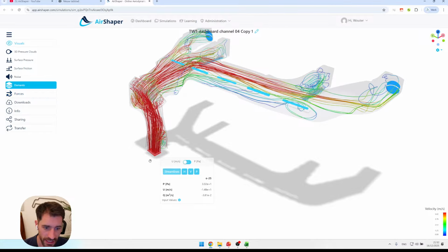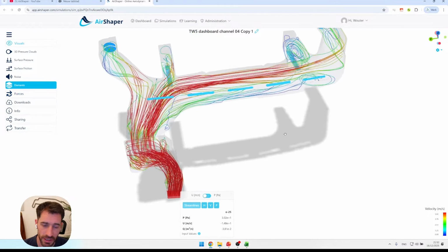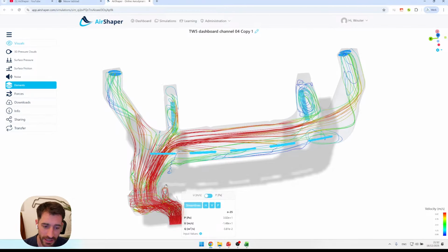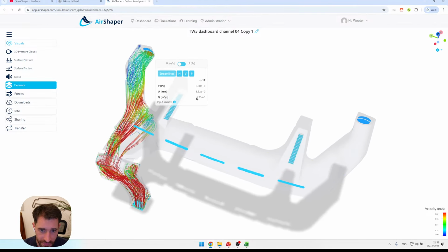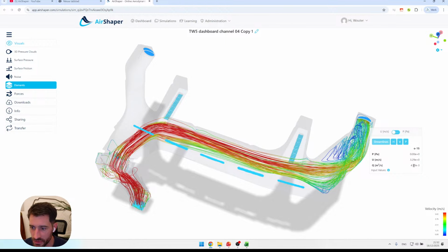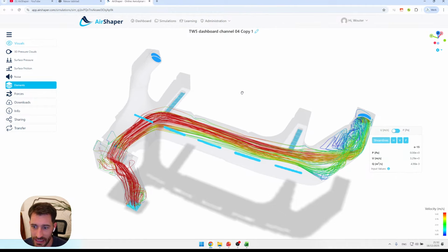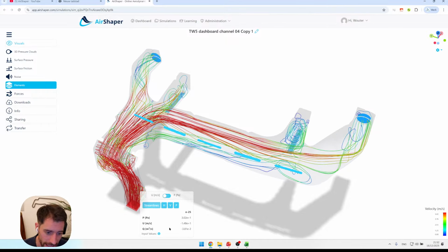If I then click the inlet in the results, I can automatically see the streamlines, the distribution of the flow lines, see where the highest momentum airflow is going, and see where you have pockets of recirculating air. If you click the outlets, you can analyze the flow rate on the outlet and see that there's just a 10-20% delta, maybe, in this design, and it's still ongoing. And if you click on the inlet, you can also analyze your pressure drop, which is useful input for your fan selection. Because you want to know for a given flow rate how much pressure buildup you need, and once you know those key parameters, you can start selecting your fan.